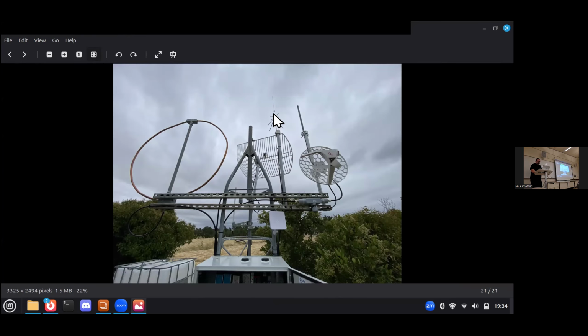that's a discone for the VHF and UHF stuff, just because it's wideband and was easy to put up. This one is a dual band 1090 and 978 antenna, so I can get both ADS-B and UAT stuff off of it. The HF loop, it just seemed like it was going to be easier to set up than a long wire or a fan dipole or something like that, especially because it was just doing receive only. The antenna, well, I replaced the grid with the Discovery dish because it was going to be easier to get it pointed properly.